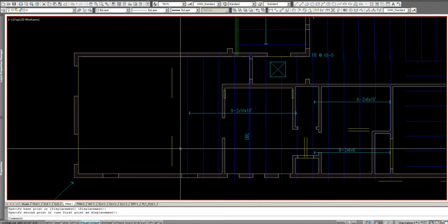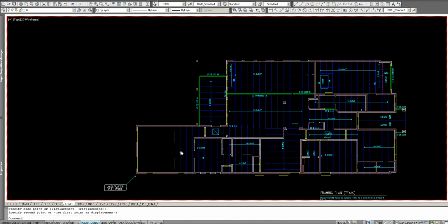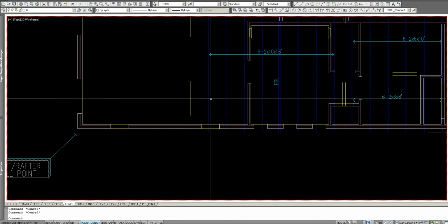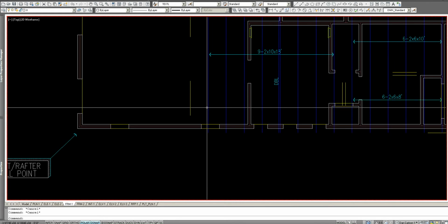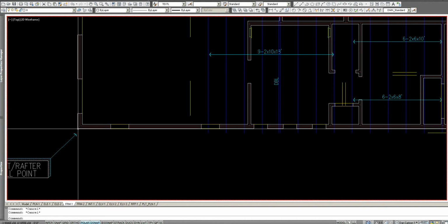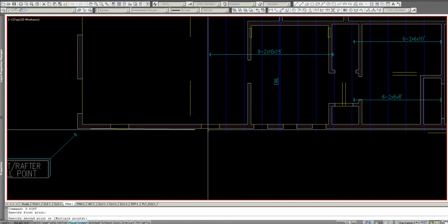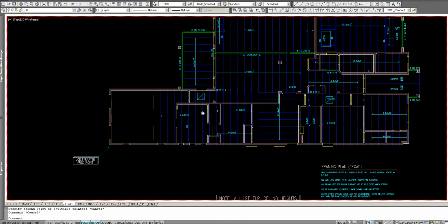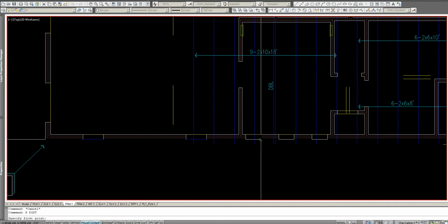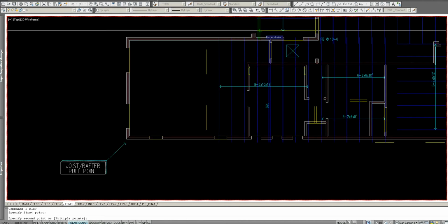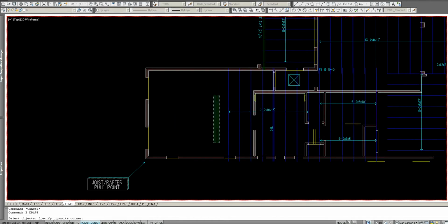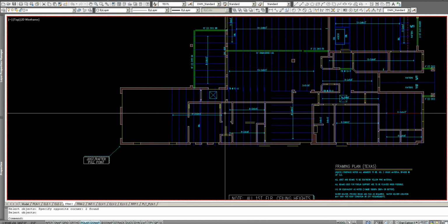And you can see as I had moved doors, and I modified this plan quite a bit, some of these headers got left behind. I'm also just going to check real quick and see where the previous joists were. Is it still on a 2-foot increment from this corner? So I'm going to measure over, and it's at 14.6, so it's not. And I know I shrank the house, so if I measure from that same point up, are these at an even number? That's 17'8". It is off as well. So we are in essence going to have to start over on this.